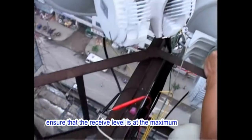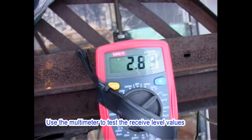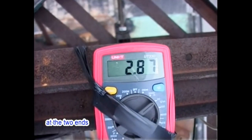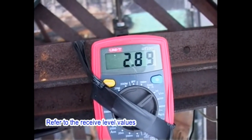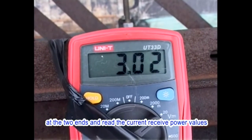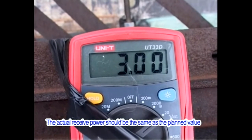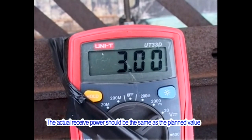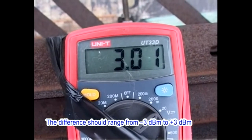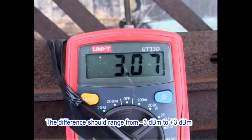During the tightening, ensure that the receive level is at the maximum. Use the multimeter to test the receive level values at the two ends. Refer to the receive level values and the received signal level curves of the ODUs at the two ends and read the current receive power values. The actual receive power should be the same as the planned value. The difference should range from -3 dBm to +3 dBm.